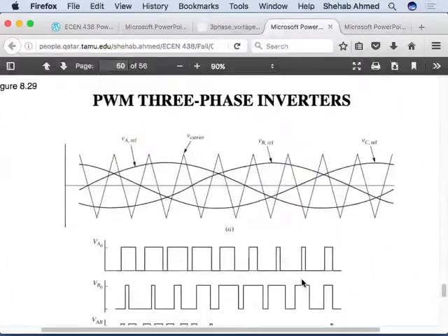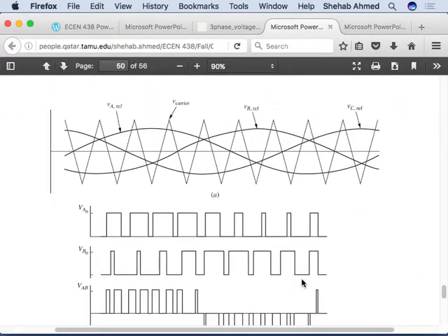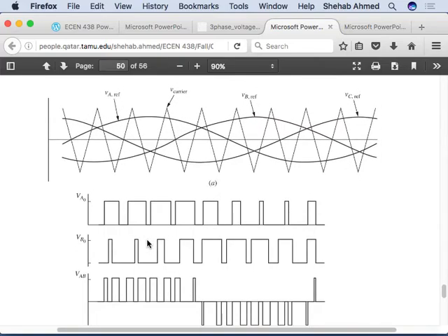Then people started using multiple pulses per cycle. Multiple pulses per cycle in three-phase inverters can go through the same logic we did before. You can add 2 or 3 pulses that you calculate offline. Or people have advanced to the level of understanding sinusoidal PWM better, and understanding this concept of changing the modulation ratios, or the D1, D2, D3, the same way we varied them, and how this creates an output voltage waveform that looks like a sine wave. It looks very well like a sine wave when you average it out through a filter, right? So that's called sinusoidal PWM.